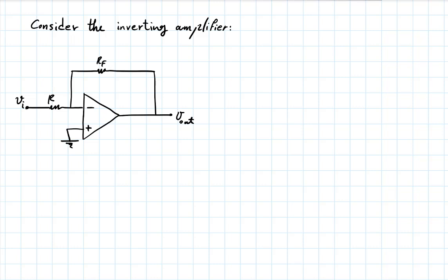And the voltage difference between the two inputs is multiplied by infinity to give you the output voltage. Now, if you've built a circuit in such a way that the output is not infinity, or in practice, not saturated to one of the supply voltages, then it means there should be no voltage difference at the input. Because a finite V out divided by infinity should give you 0 as the voltage difference between the two inputs.